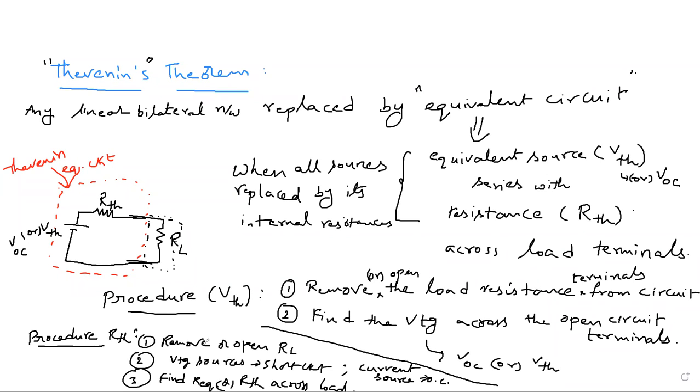You can understand well. Similarly, RTH is nothing but the same. We can follow the first step of the VTH procedure. And in the second step, we are finding the resistance, Thevenin's resistance. Therefore, we are keeping all the source values at 0. If there is any internal resistance present, then we can replace those sources with their internal resistances. But the majority of the problems don't have voltage sources with internal resistance, so we can directly go for turning off the sources in the circuit to calculate RTH.